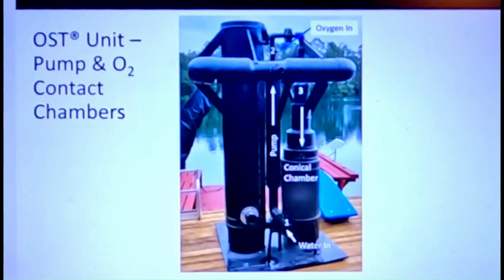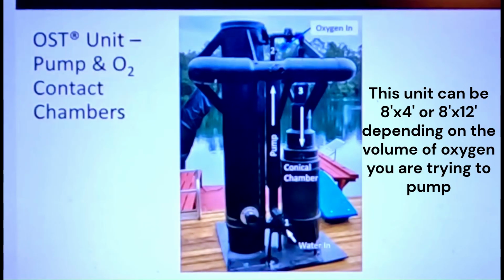And the reason why we have that is as the water hits a larger diameter pipe, its downward velocity decreases to the point where it matches the rise velocity of a bubble. And that's the point where we get really good oxygen transfer. The water then continues down across the bottom into our secondary chamber. We call this our BCS, or our bubble capture chamber.